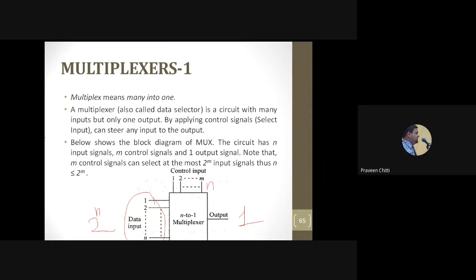The smallest of all the multiplexers is what? When N is equal to 1, we get the smallest of all multiplexers. When you put N equal to 1 here, how many inputs will you have? If you take N equal to 1, then we have 2 to the power 1, equal to 2 inputs. And how many select lines should you have?